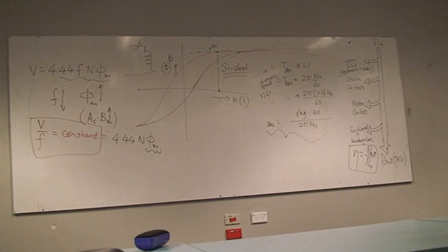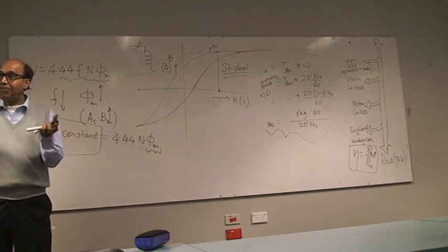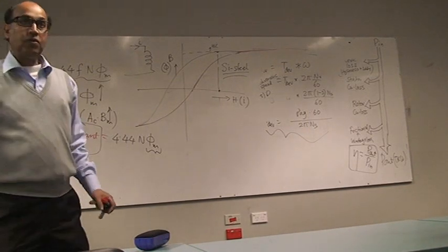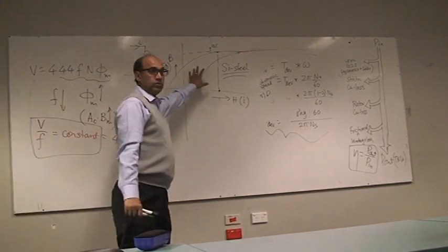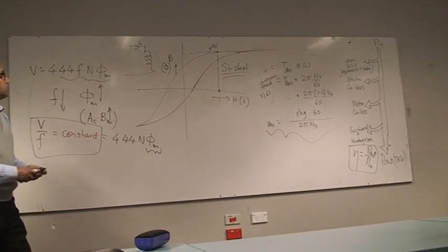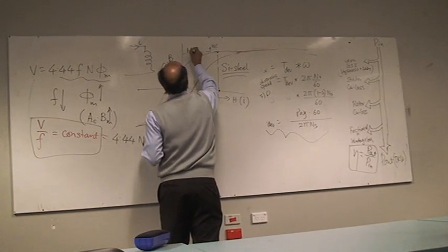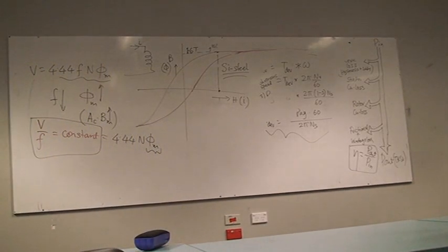So you talked of superconductor. A superconductor is replacing your winding coil. Okay? A superconductor does not replace your core. Your core is the material which actually provides the path of the flux. You produce the flux with the superconducting coil, but that flux has to go through a path. That's the path you get from the core. So silicon steel is the material you use, and this maximum value is around 1.6 Tesla, which is the maximum flux density you get.